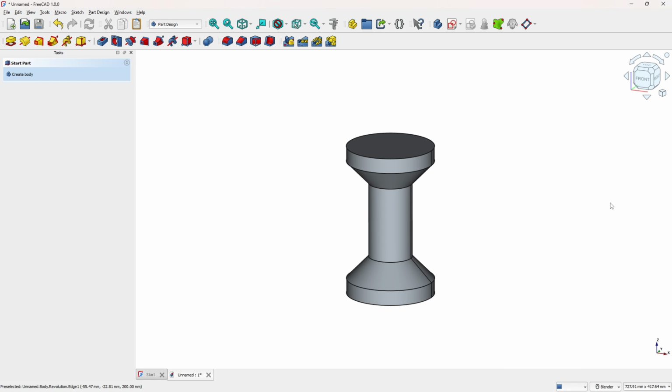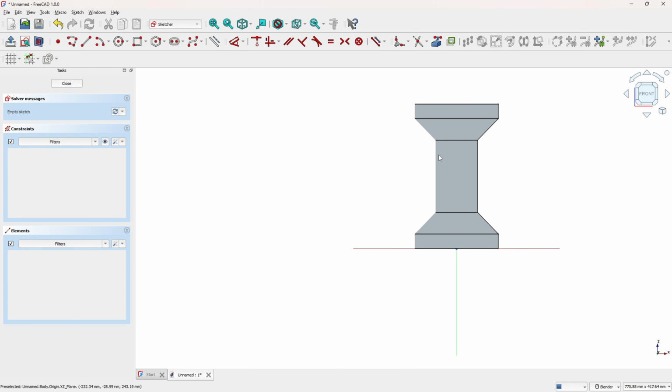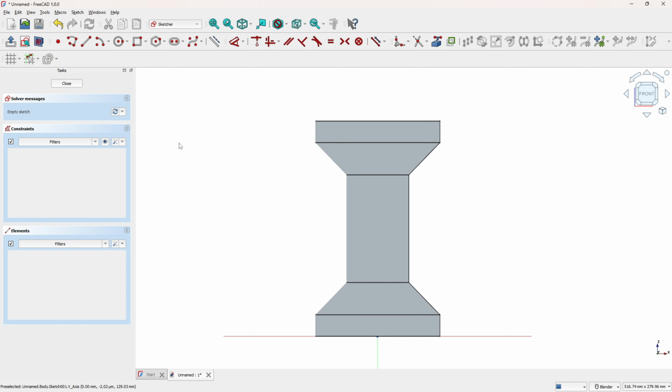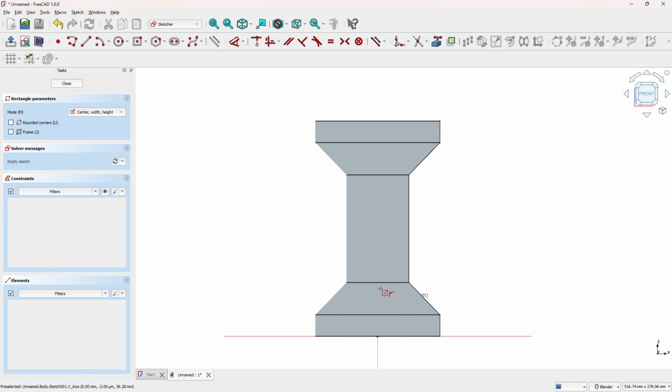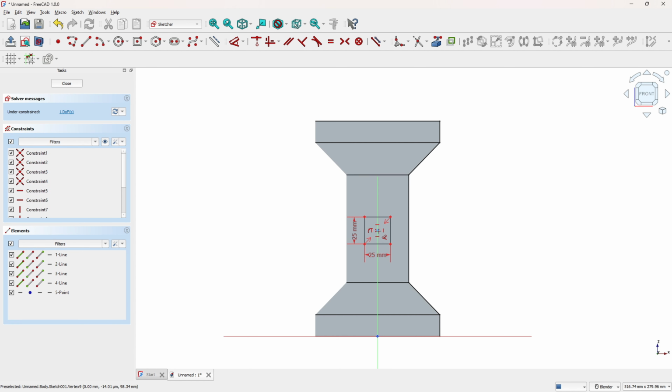So go to create a sketch, select the XZ plane. And here select a rectangle, center rectangle. Make a rectangle here. Click here in the view section. Click here in this line, make a rectangle here, 25 by 25 millimeters. Now go to dimensions, select the center of this square. The distance here is 100 millimeters. Now leave the sketch.